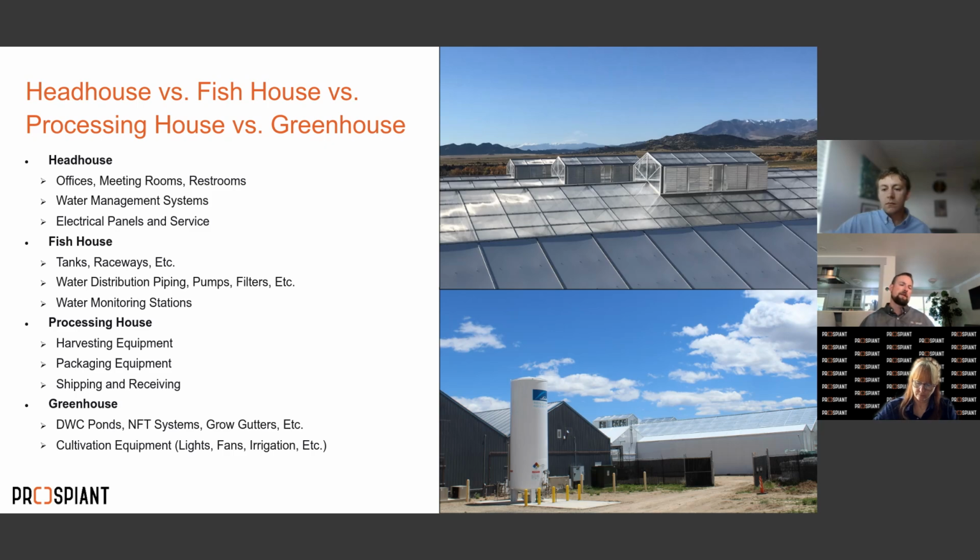Two different ways of doing the same thing. It's just how do you want to exercise your fish and keep those tanks clean, and how much water do you want to push through those tanks? What's the retention time of each tank need to be? And that all comes into the sizing of your equipment. So the sizing of your pumps, how you're delivering oxygen to the tanks, how many fish you want per tank, what your housing capacity is, your holding capacity is. So those all come into play when sizing the stuff that goes inside of the aquaculture building, or what we call the fish house oftentimes. Mm-hmm.